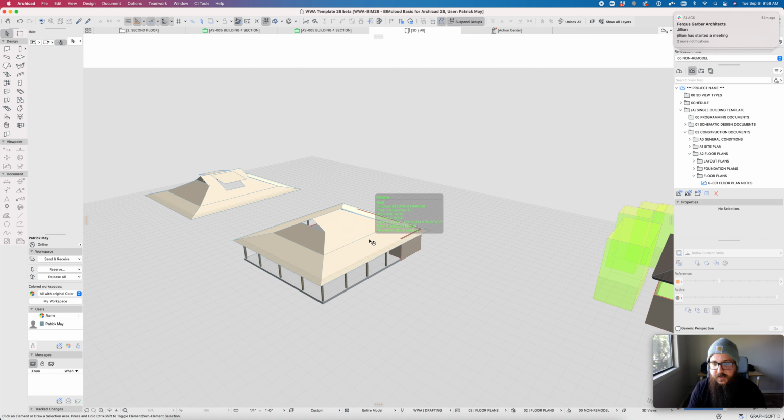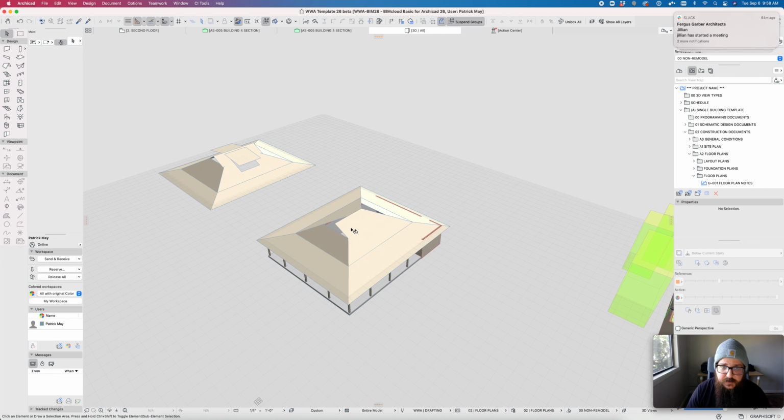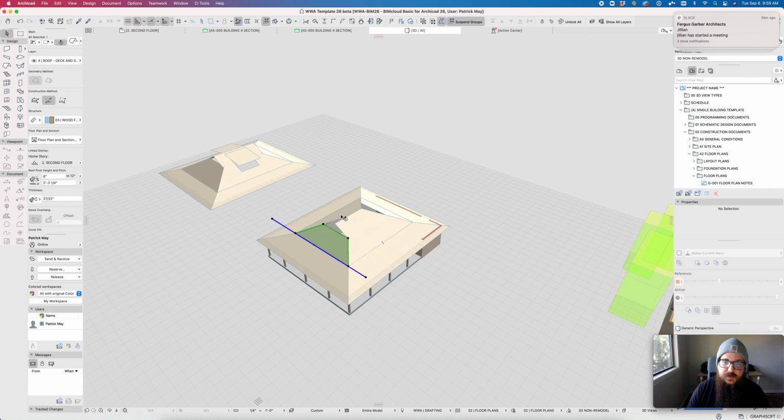Anytime you have multiple plate heights, anytime you have complex trimmed dormers and things like that, the multi-plane roof, you cannot use that Command-click trim to trim roofs to roofs. So joining complex roofs with the multi-plane roof is a little bit too finicky, and we would have to split to single-plane roofs or start modeling from scratch with single-plane roofs.